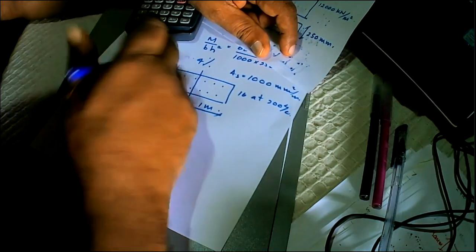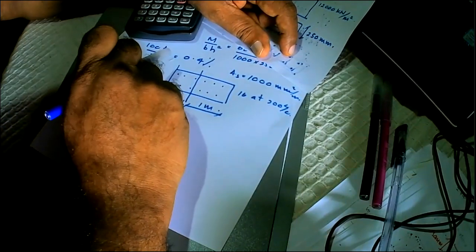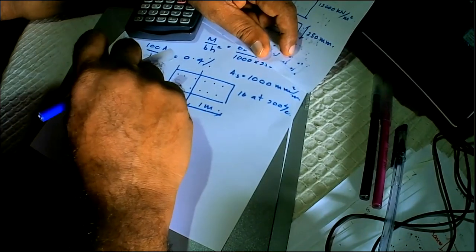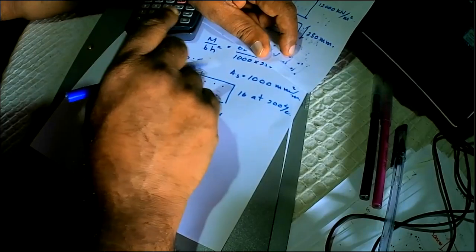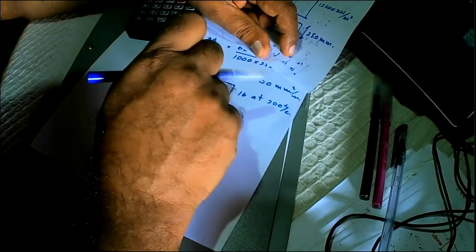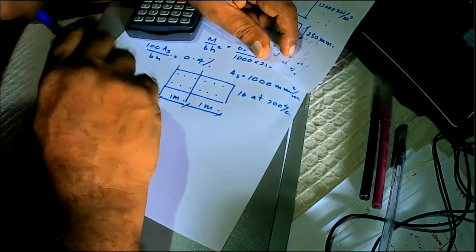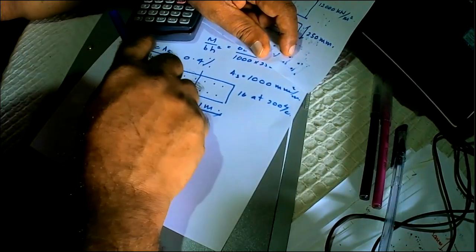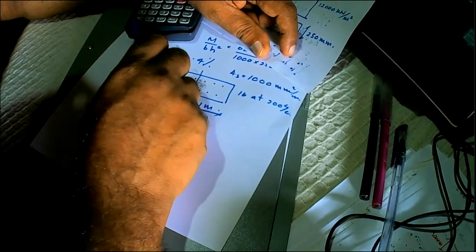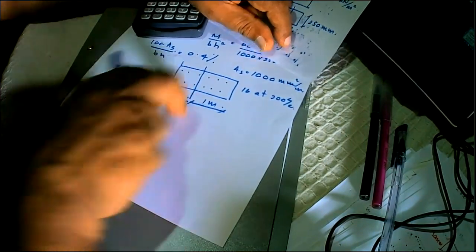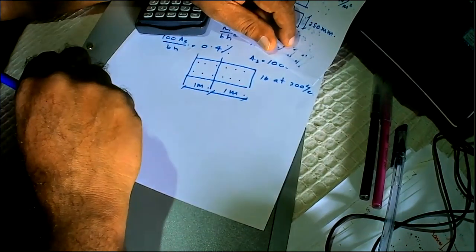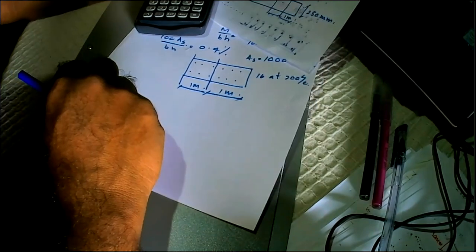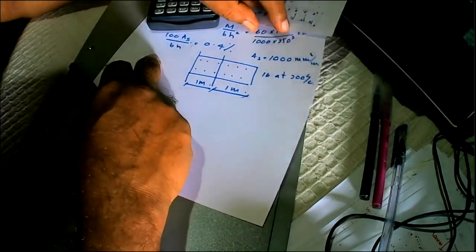for Eurocodes also you get column design charts where the equation is slightly different, because what we find is N over b h f_cu, f_ck, something like that. So basically the method is the same, and if you know the overall moment and the axial load, you can find the reinforcement, considering it as a column. On the other hand, if you know the stress distribution, again you can find the reinforcement by considering 1 meter length of the wall. Is that clear? So there are two different ways of finding the reinforcement.